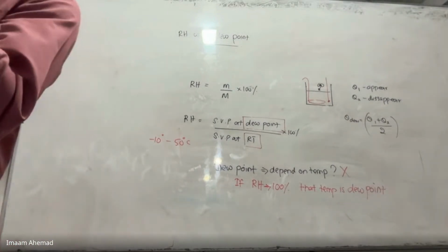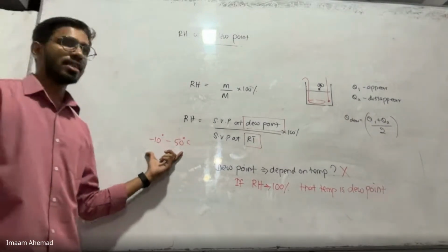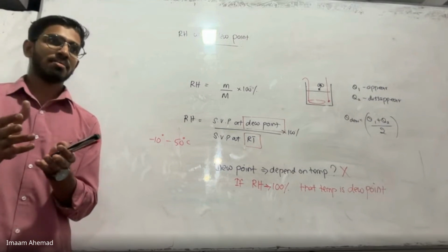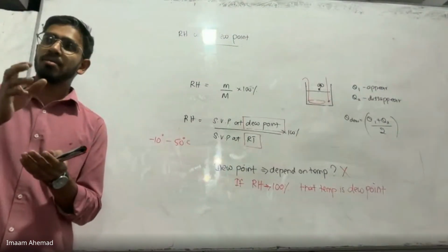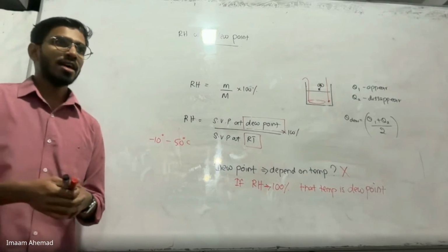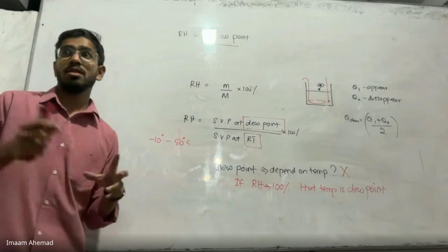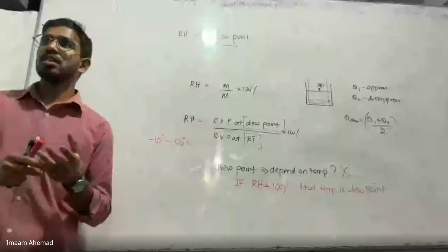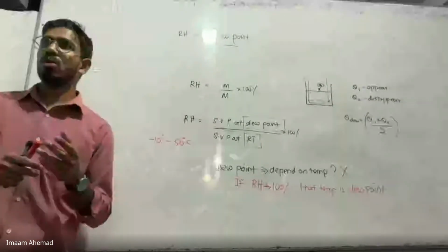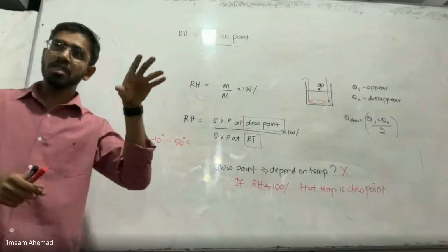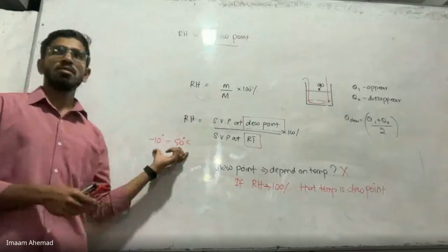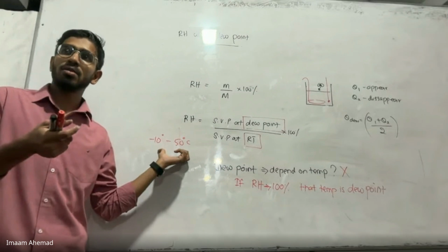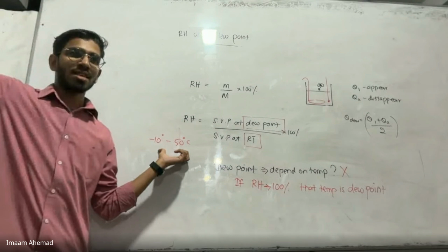When you are using this thermometer, you have to be careful about the mixture's temperature. You should have an idea about the mixture temperature. Now this is the method of mixtures experiment, and the temperature is going to come close to 50. In that situation, can I use this thermometer? Can't. What is the thermometer I have to use? Minus 10 to 100. Okay.